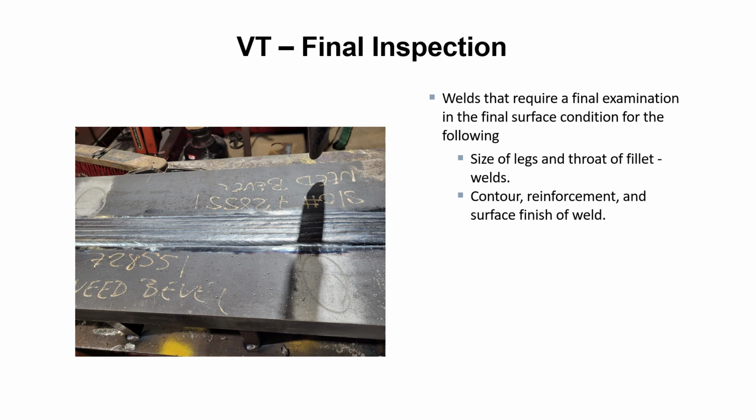Or, all right. And usually if the weld looks absolutely horrible, that doesn't mean that it's always rejectable, but it can mean that you've got other issues involved with it. If you've got a lot of issues with the surface of the weld, that can also mean you've got a lot of other problems with what's going on. Just something to think about.